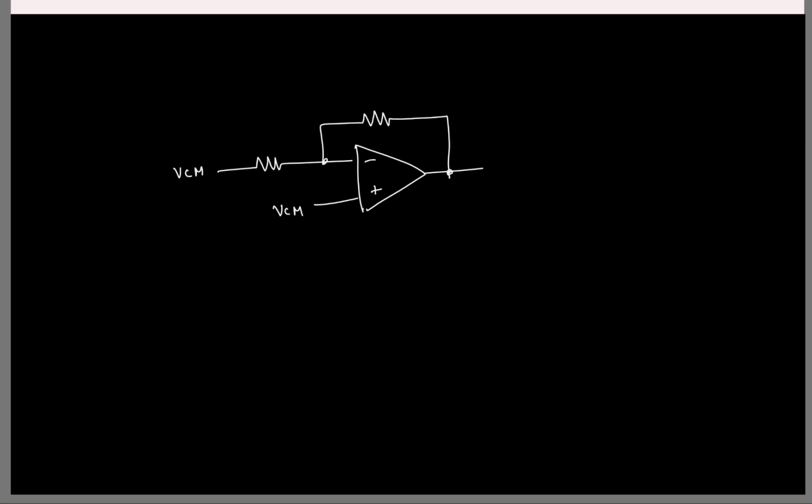Now what is setting this virtual ground voltage here? Yeah, it is set to VCM, but what is enforcing it? The negative feedback. The DC negative feedback around the op amp is setting this to VCM. So what should be the current flowing here? So what should be this voltage? VCM. So here what is setting my common mode voltages?